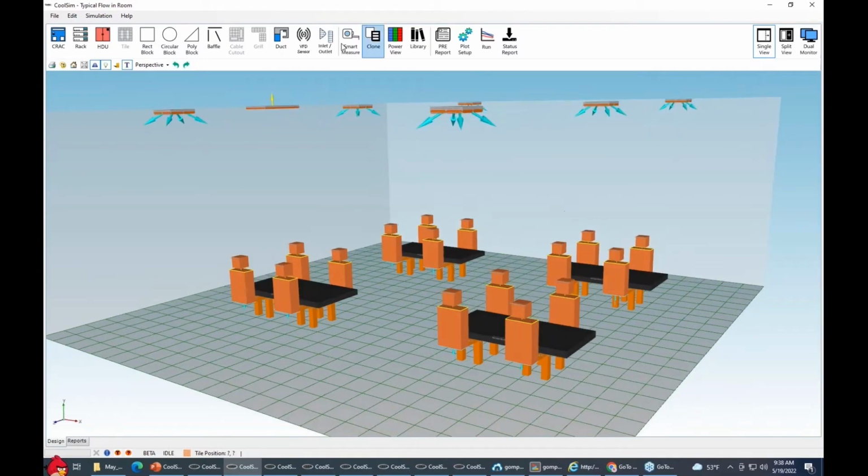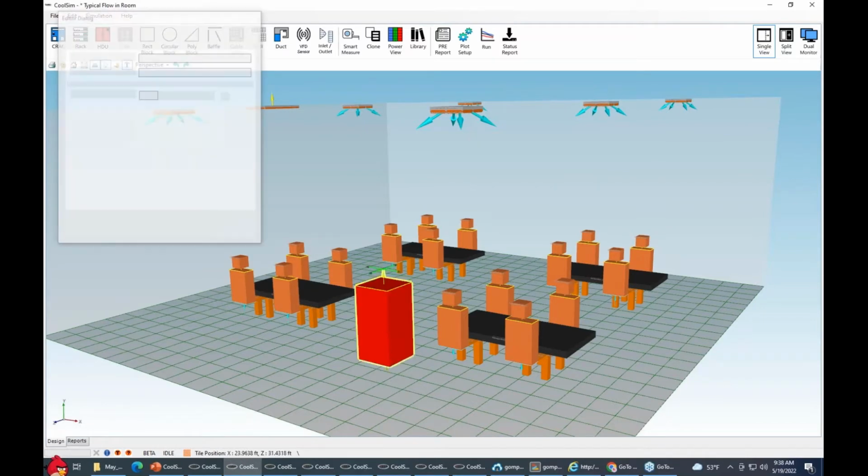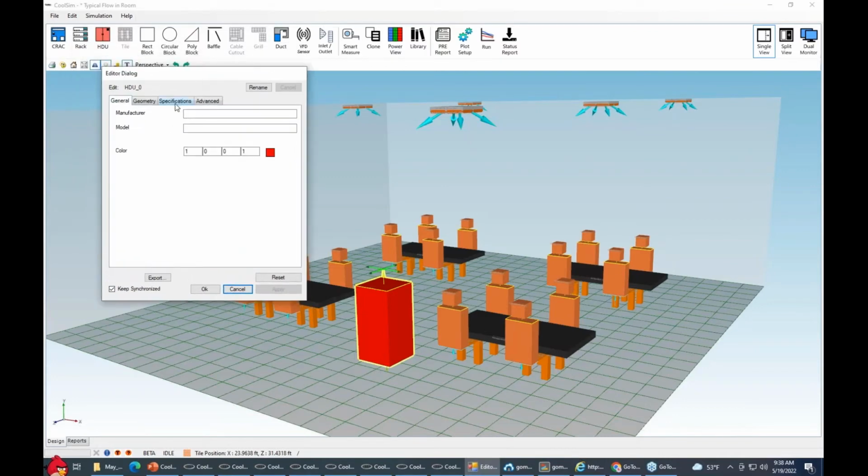We have, by the way, generalized the PDU structure. So it used to be, we called it a PDU, and we didn't allow you to set the delta T on it. We had it early on in CoolSim and then took it out. We've added it back in. So you can now set the delta T on these. This becomes very handy for modeling condensers or heat exchangers for air-cooled chillers. We'll get into that in a moment.